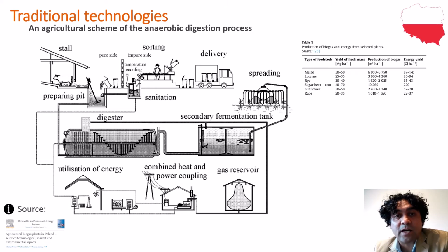Larger sets are also used in agriculture. For example, in the case of processing of up to 10,000 cubic meters of feedstock per year, the digester chamber has a volume up to 1,000 cubic meters, contains 2 or more mixers, and has a roof with a double membrane that forms the gas tank.